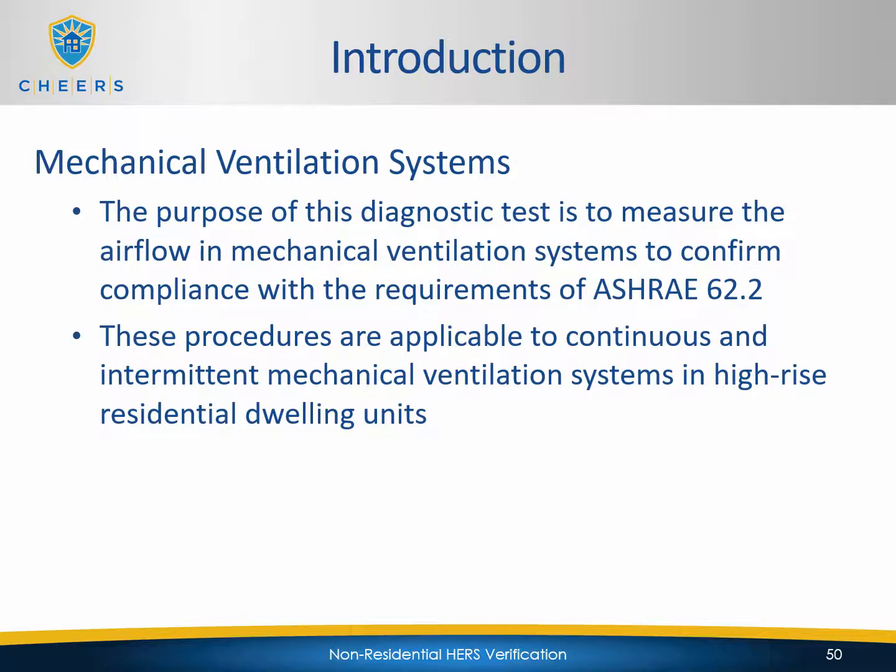Mechanical ventilation systems. So the purpose of this diagnostic test is to measure the airflow in mechanical ventilation systems to confirm compliance with the requirements of ASHRAE 62.2. These procedures are applicable to continuous and intermittent mechanical ventilation systems in high-rise residential dwelling units.